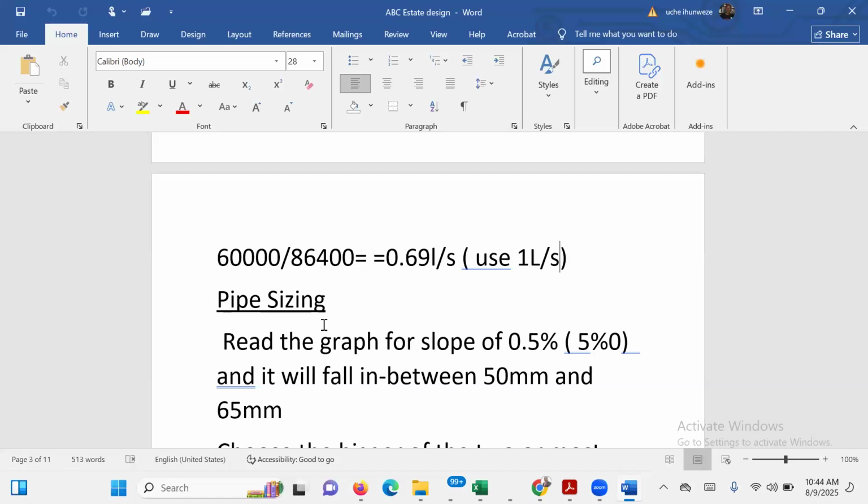I don't need to tell you, it depends on this velocity, this slope. So that's why last week I gave a general advice that the minimum pipe size in your network, in your infrastructure work, should be 75 mm, 3 inches pipe. Don't use 2 inches pipe. You can use 2 inches pipe within the house, but for outside the house, the ones you lay on the road, on the street, let your minimal pipe design be 3 inches. Then of course you can increase as you go towards the source.